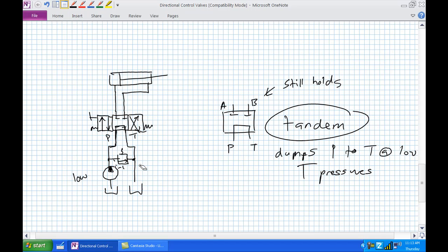Okay, let's say this is a system where objects of varying size are coming into this thing, and you need to hold it. With objects of varying size, you would have to go ahead and activate it and slowly move this rod in for this thing, and then for this thing there. You couldn't do that, or you couldn't grab onto the rod and move it to hit any one of those objects of varying sizes in that closed center position. So there's this other position, a center position, called a float.